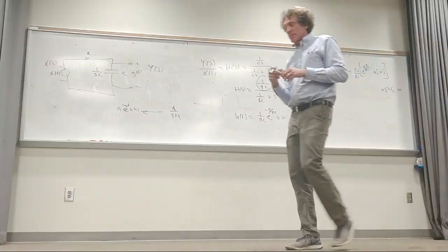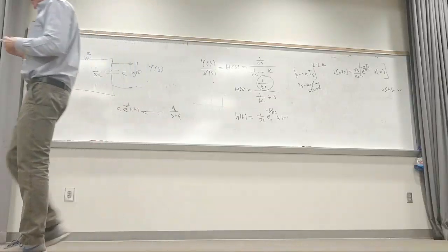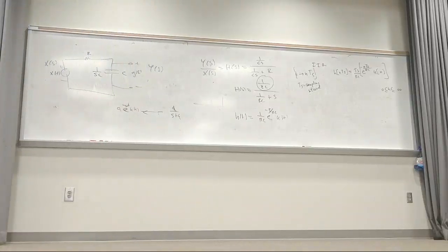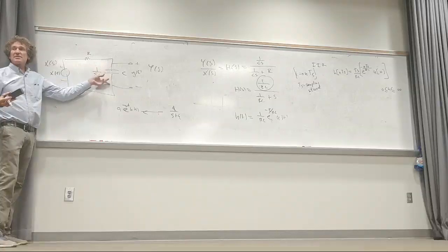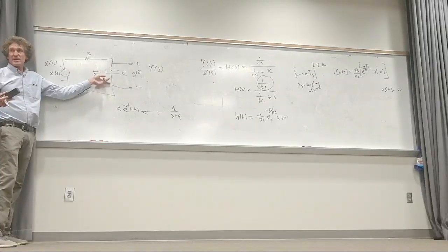Take a look at it. Just look at it here. Simple. Is it high pass, low pass, band stop? Pardon me? You all see it's low pass? Here's how you can always tell. Just look at what the output of this is going to be as frequency goes to 0. You know, a capacitor looks like an open circuit for 0 frequency or DC, right?